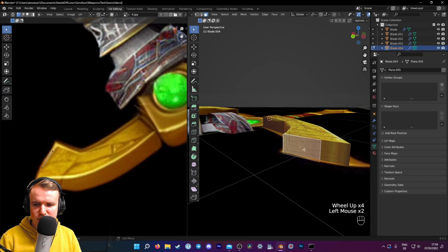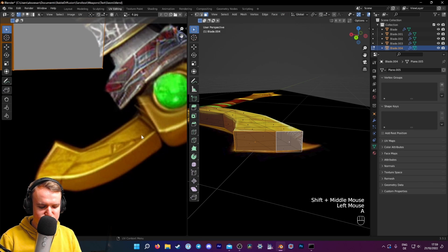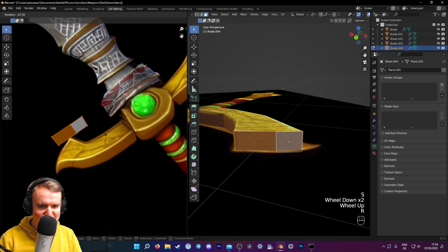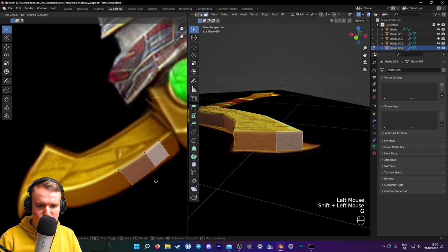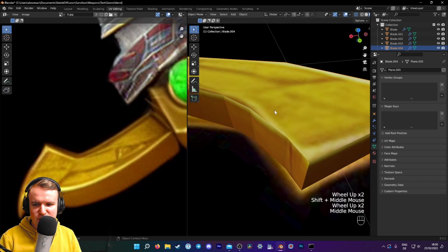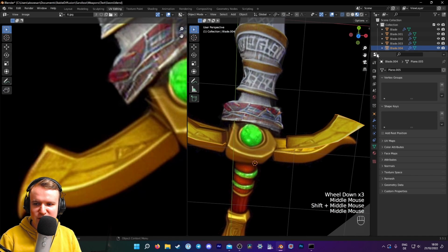And the same procedure on these two. Just UV project and find a spot that might look like it could work. It could look similar. And I'm thinking that's probably this area here, right? We have a bright corner up there. And just stretch that down. And already you can see, it's not incredible, but it's decent enough that we can paint over it later in Photoshop or in texture paint, depending on what we prefer.